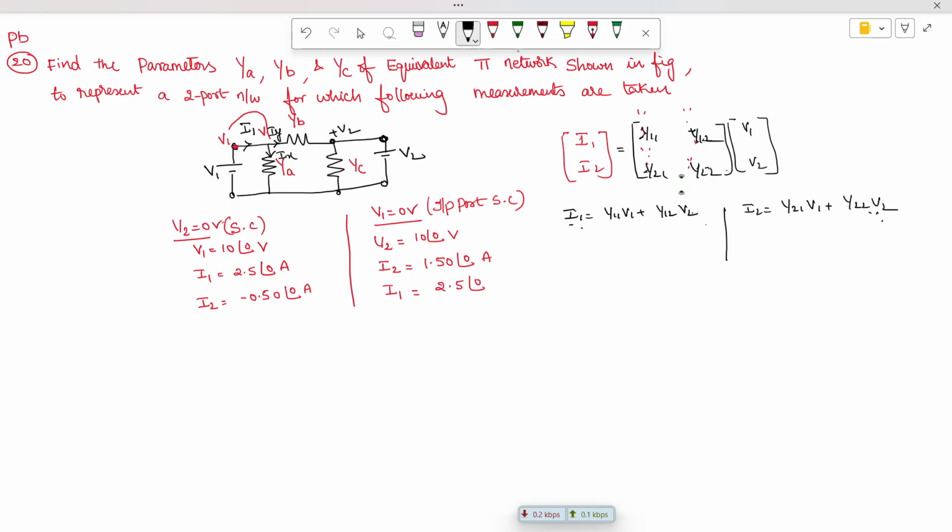So now when you carefully apply here, we are going to apply Kirchhoff's current law at the node V1. What is the entering current here? The entering current is I1 and the leaving currents are Ix and Iy. You can see the current in this branch is Ix, the current in another branch is Iy. Already we solved this in our channel, you can visualize there. Why I am solving it again is because these two are also required, that's why I'm doing it by one more method.